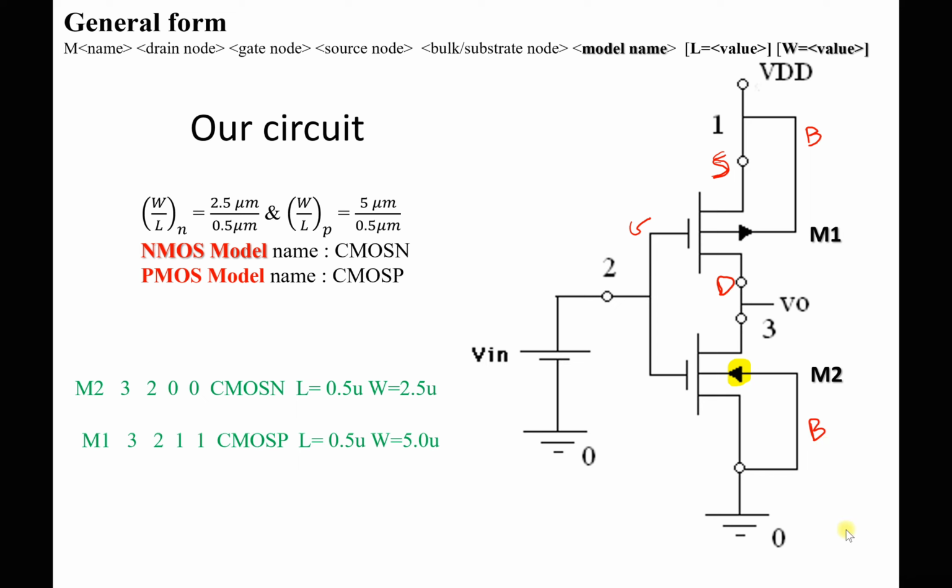And here I have defined it as I said just now. Now, if you have a circuit and you want to identify whether it has an NMOS or PMOS transistor, look at the bulk. If the bulk arrow is pointing into the gate, it will be an NMOS. If the bulk arrow is pointing out of the gate, it will be a PMOS.